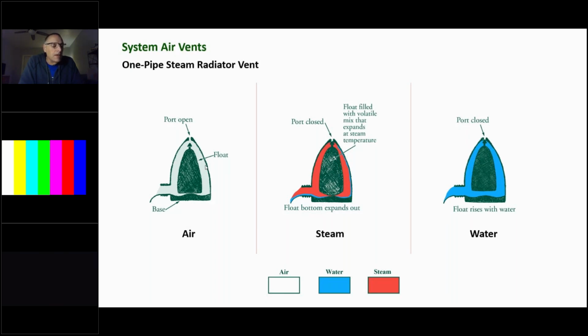So obviously no one pipe steam system should be operating anywhere near that, but it has an operating pressure of 1.5 psi. So if you show up and the pressure control is set, say, at a 2-pound cut in and a 4-pound cut out, which a lot of times people try and do. They think if they're not getting enough heat in the house, well, we're not producing enough pressure. So let's go down and raise the pressure on those controls and see if we can get more steam out to the house. The opposite is, in fact, true. Dan Holohan had a mantra: "turn it down, crank it down." Crank those operating controls down. So again, the operating pressure is 1.5 psi on a 1A valve.